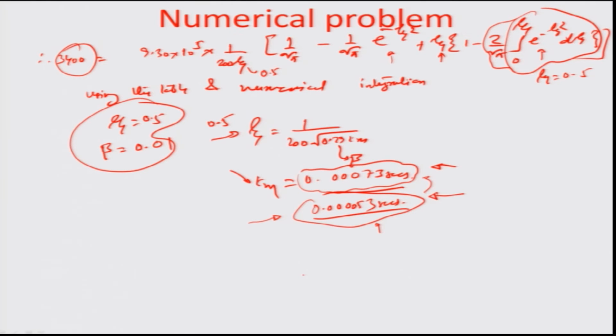So as we see here, this is more accurate and more appropriate in terms of when the machining should happen. Typically, the start of machining is when the center of the spot on the surface of the material being machined comes to the melting point, and beyond that it is about how heat conduction would happen from the surface onwards, and how the melting zone would recede, so that a cavity is formed.